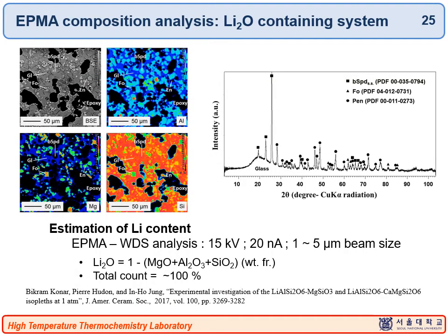The next challenge is the EPMA composition analysis. Of course, EPMA is an extremely useful technique for phase diagram study, but it cannot detect lithium, and sometimes other alkali content and fluoride content may not be accurate. Then we have to prepare our own standard sample for the analysis and confirm our analysis result.